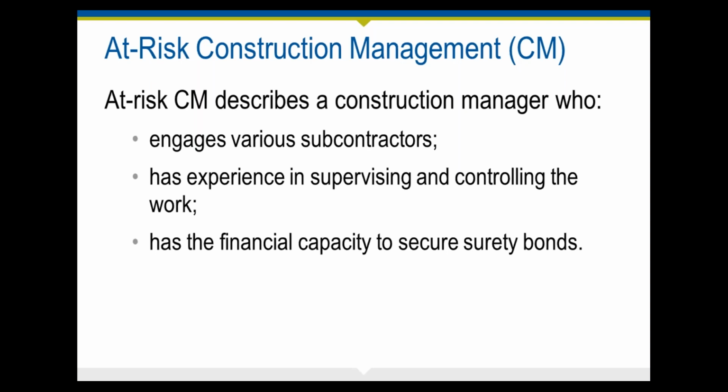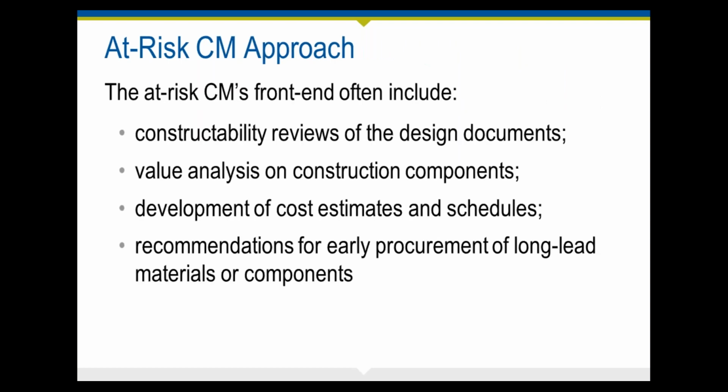So, with that said, the at-risk construction managers' front-end or pre-construction services often include constructability review of the design documents, value analysis studies on major construction components, development of construction cost estimates and construction schedules, recommendations concerning early procurement of long lead construction materials or components. So what that means is that the design professional is still providing consulting services to the client.